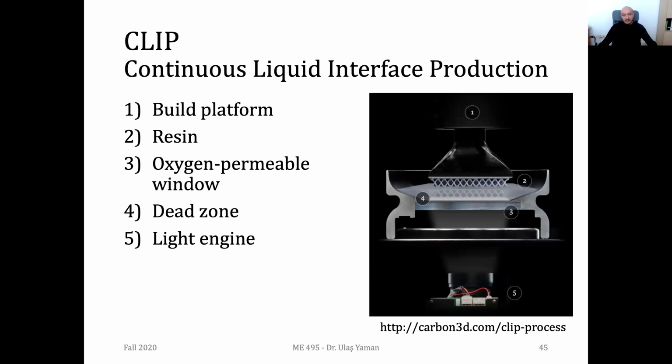Yep, the solidification is actually the same. They are again curing the photopolymer, but they are curing it in a faster way with the help of this oxygen permeable window. No, they don't have a laser. They have a light source, a kind of a projector, like a kind of a screen underneath.